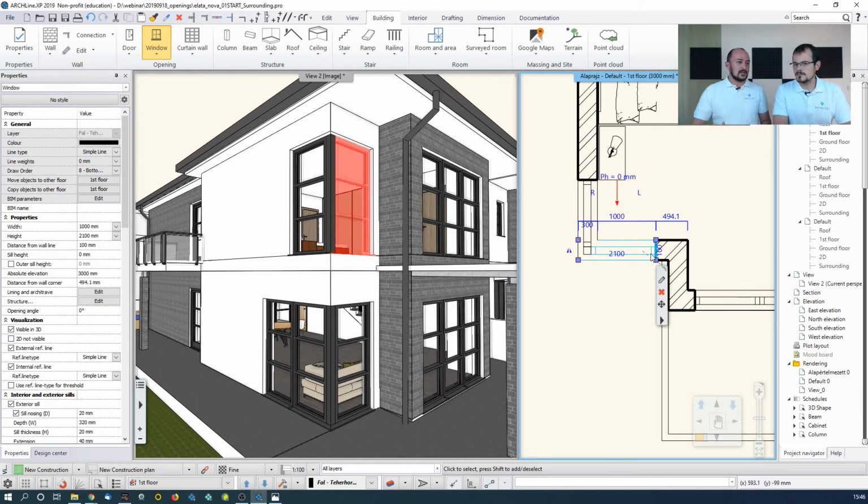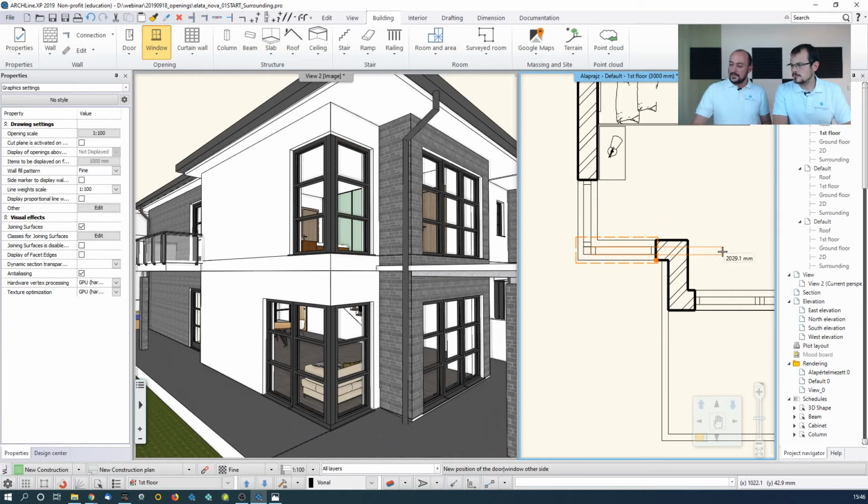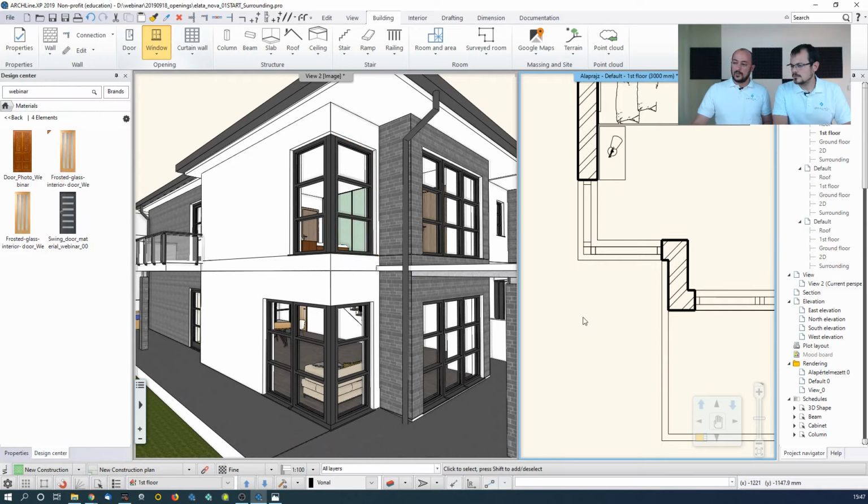This is something that we didn't discuss yet. You can move the window, you can flip it around, you can change the window type, but you can actually click on the corner as well and change the size, either by typing a value or just snapping it to an existing drawing part. And I know it was there originally, so I just click here, and then I create the new window shape as it is now. Yes, perfect. We might return to this issue later on because of the questions that we are being asked.